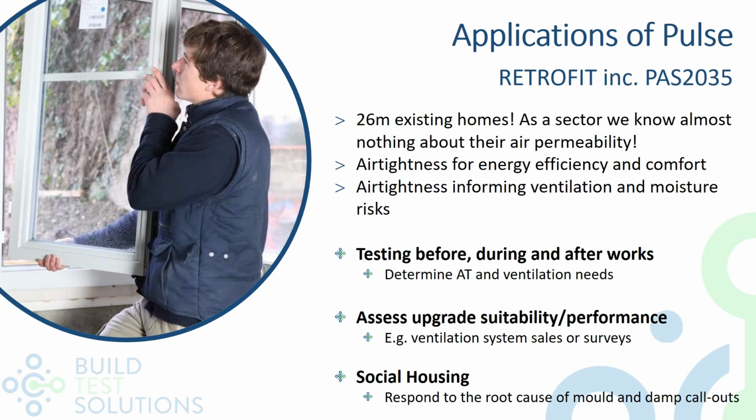There's also retrofit. Air tightness testing has been far less prevalent in existing homes, regardless of the pressure level, so there's a tremendous amount to learn here as well. Use cases for Pulse include testing before, during and after works to determine both the air tightness but also the ventilation needs of a building, assessing that background ventilation.